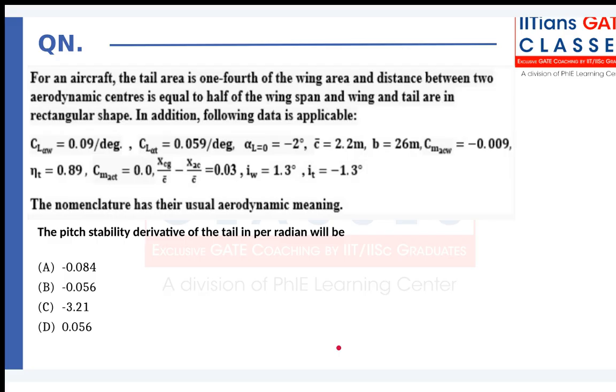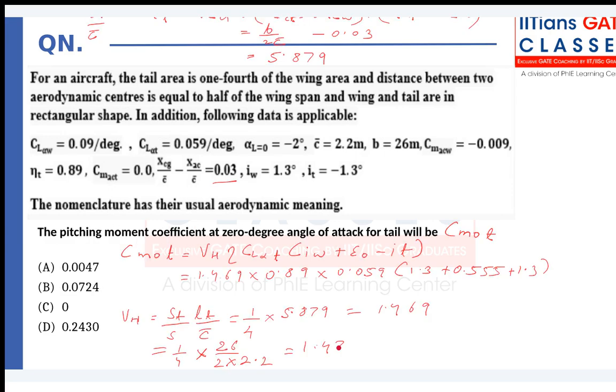Yes, did you have a question? Or do we know which unit to give our answer? Okay, so in this equation, if you take your CL alpha tail to be in per degrees, you need to make sure that your angles are in degrees.